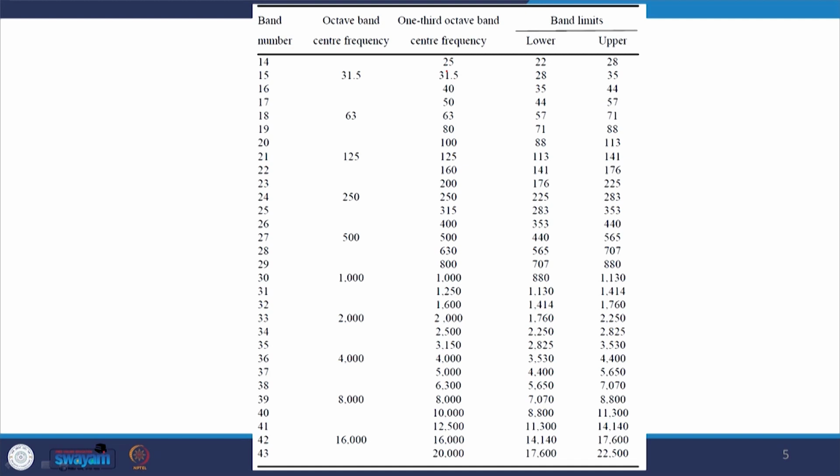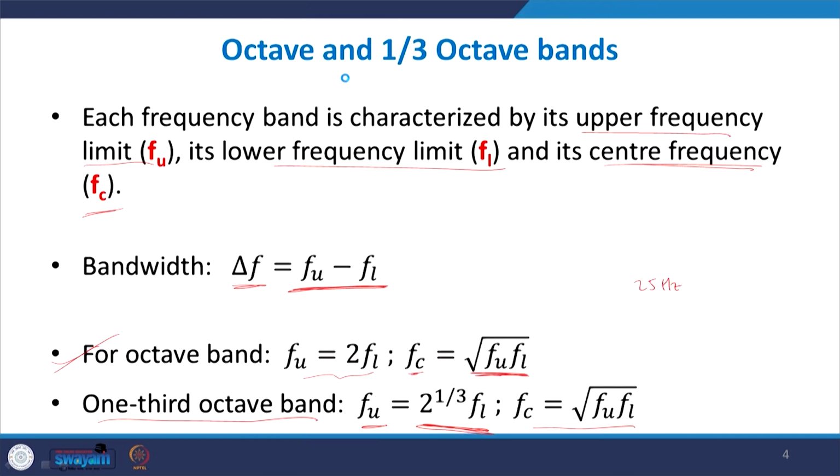This table lists the bands, giving the center frequency for a particular band. So we have a band from, let's say, 25 to 40 Hz. The geometric mean occurs somewhere around 31.5 Hz. Every band has two limiting frequencies, but the center is taken as the center frequency, and for easier notation we simply denote a band by its center frequency.